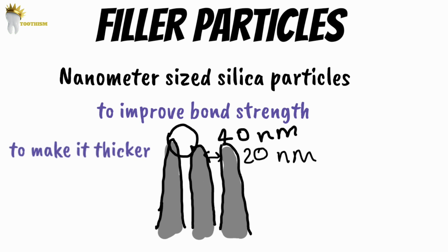The other reason for the addition of fillers is to make the adhesives thicker in consistency because thick adhesives form a thick bonding layer which can promote increased bond strength. Also, a thick adhesive layer can reduce shrinkage stress.